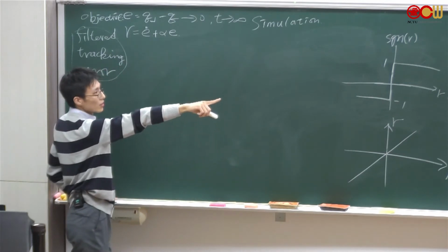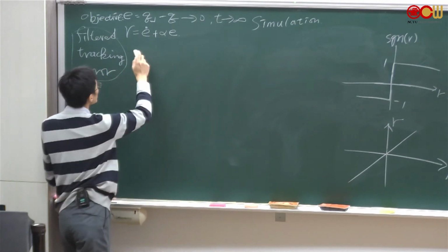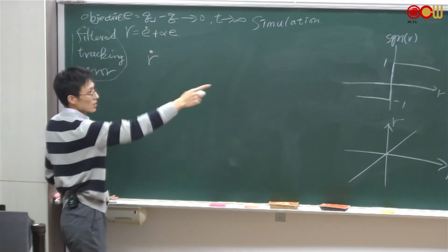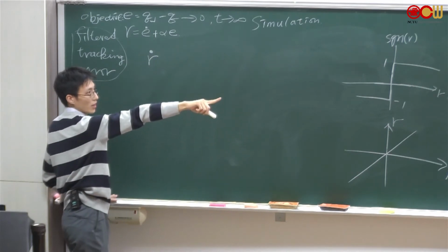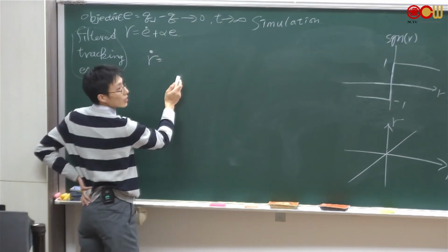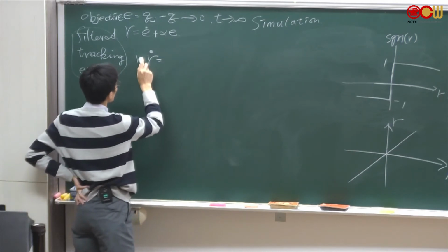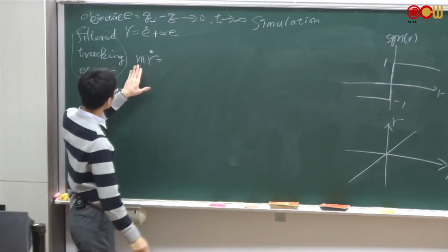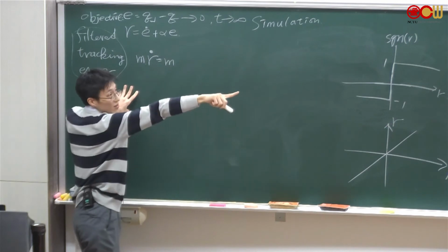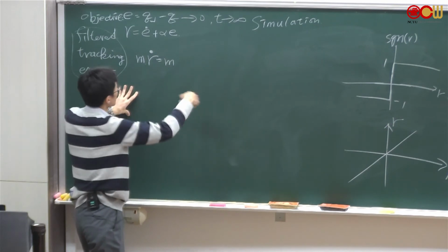So that is the open loop dynamics, right? And we need to find another open loop dynamics because that will be substituted into the V dot, the time derivative. So we want to find what's V dot. Okay, and maybe you put mr dot would be better. So mr dot, because there's another m in front of the q double dot, right?